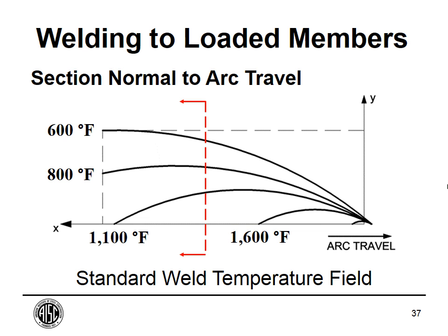But if you're 3 inches from the weld, which is, I believe, roughly where the interpass temperature should be measured, if I remember right, it's somewhere in that range anyway. It's going to take a good bit longer. I would say a couple of minutes at least before you could touch it, that far away, 3 inches away.